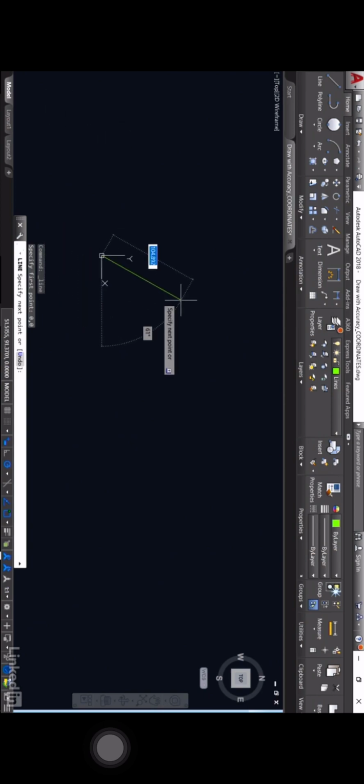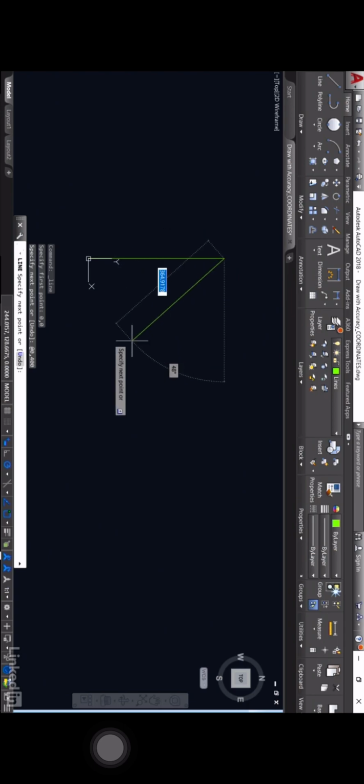And what we're going to do now is type coordinates for each corner of the square. Now the square is going to be 400 units by 400 units. So I want to go vertically upwards. In this particular case, I'm going to type 0, 400. So 0 along the x-axis, but 400 up in the y-axis. When I press enter, you'll see that draws a vertical line. Again, it's a bit big, so you might want to zoom back a bit and pan a bit, so that you can see what you're doing.